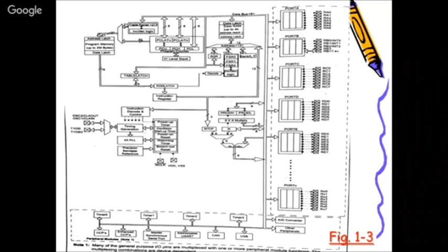This is not very clear to you, but I'll just try to tell a few things, then we'll move forward, because बाद में और अच्छे figures हैं. So in this mainly what you can see, there are ports from port A to port G. Unlike your 8051, port 1, 2, 3 नहीं बोलते, इसमें port A से शुरू होता है, A B C D alphabetically they call it port A B C D E F like that. So there are 8 ports in the highest family, and then unlike your 8051, it's not that all the ports are symmetrical कि वे सब में 8 bits ही हैं.